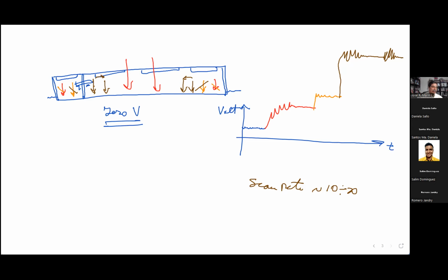And of course, we don't want that. So we have to be careful. So at the beginning, I'm going to apply a low force. Let's see what happens. And if we can apply a larger force and we check that when these two sections rotate, they don't touch up and down, we can increase the force that we apply. The two load cells have a capacity of, do you remember, Andy?